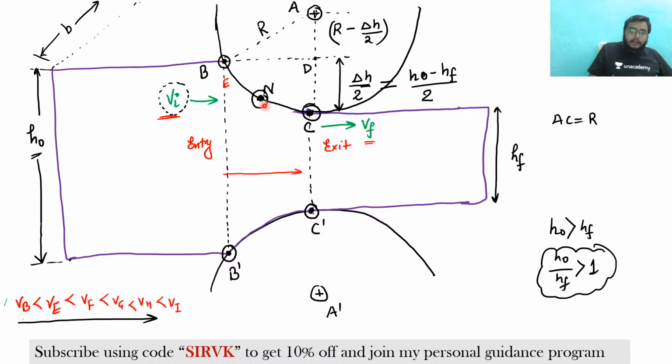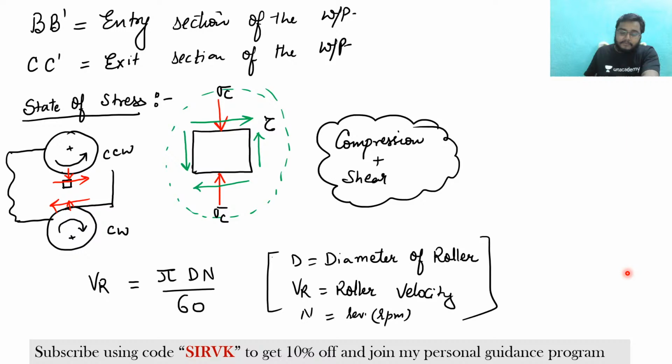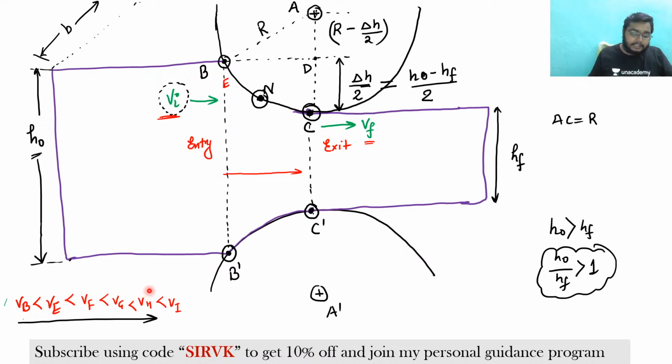See, here is the neutral point, and we have seen that the velocity of the neutral point would be equal to the velocity of the roller. We also know that VF is going to be more than VR. Just now we have derived these things: VI is less than VF, and hence based upon these conclusions I have written it like this.